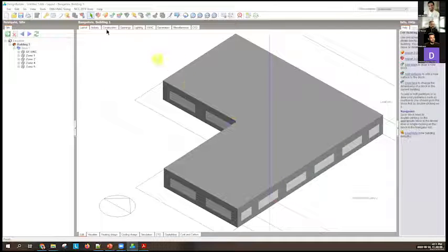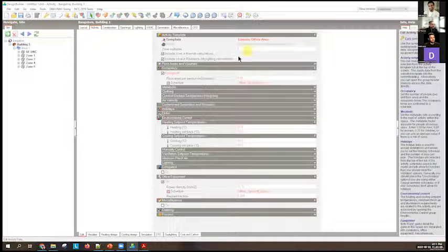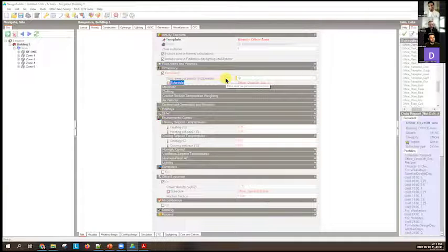So if you go to this activity tab, you can see that this allows you to specify these outcomes at the building level. We'll go through them in more detail if we have time. I can say I want 10 meters squared per person. That's a value here. I think in India it's a bit less, you have 8 meters squared per person, and so on.